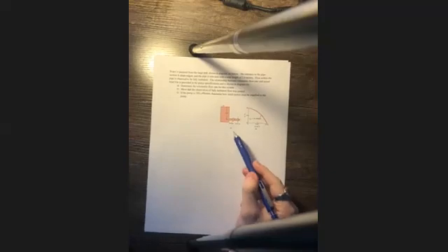The problem statement is as such. Water is pumped from the large tank shown in diagram A below. The entrance to the pipe section is sharp-edged, and the pipe is cast iron with a total length of 2.0 meters. Flow within the pipe is observed to be fully turbulent. The relationship between volumetric flow rate and actual head rise is provided in the pump specifications and is shown in diagram B.